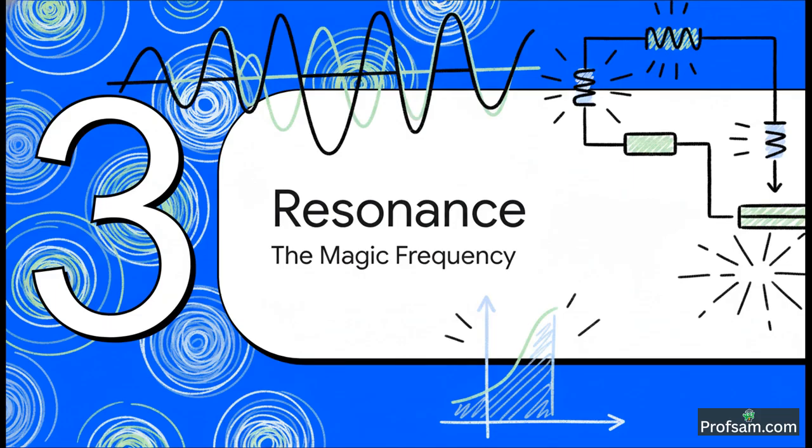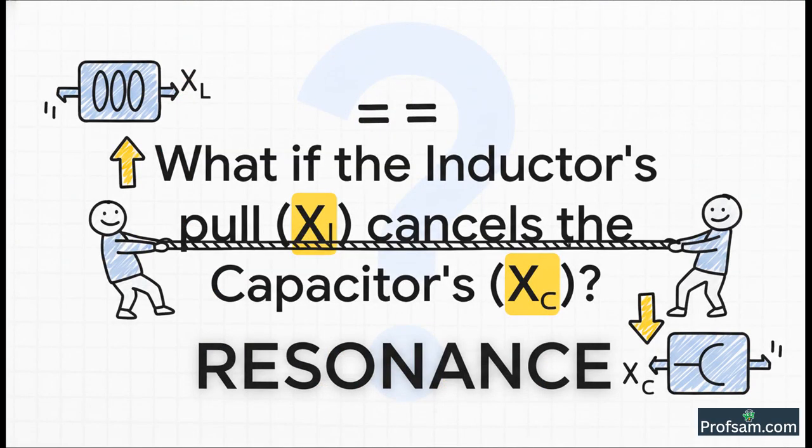What happens at one special, one magic frequency? This is really the heart of the LCR circuit. Let's ask a very important question. Look back at our tug of war. What would happen if the inductor's upward pull, its reactance X sub L, becomes exactly equal to the capacitor's downward pull, its reactance X sub C? What if they perfectly cancel each other out? This single question leads us to the most important concept in this topic, resonance.